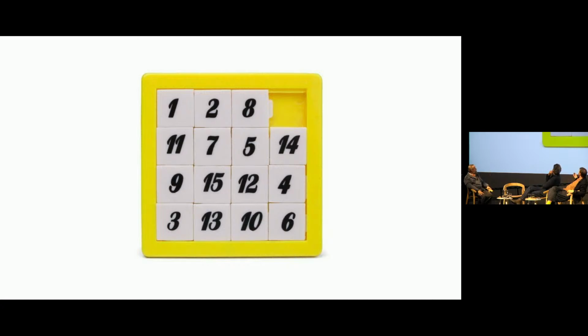So if you see here, this tile is held on that edge and on that edge, and so these other two edges are stable because it's built on two sides. When you build the next tile in, it's supported on that edge and the previous tile, and then you can put this one in, and it's supported on that edge and the previous tile. So they all interlock, kinetically locked together, and they form a structure.